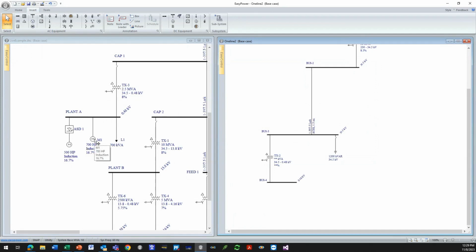Across the line motors accumulated, across the line ASD accumulated into one, and then all your static load that's remaining accumulated into a separate value. This gives you some detail down here without having to simulate the whole 480 volt network. If you're doing an analysis on the 480 volt network, you should simulate it in greater detail. Okay, you understand? This is just extra information.